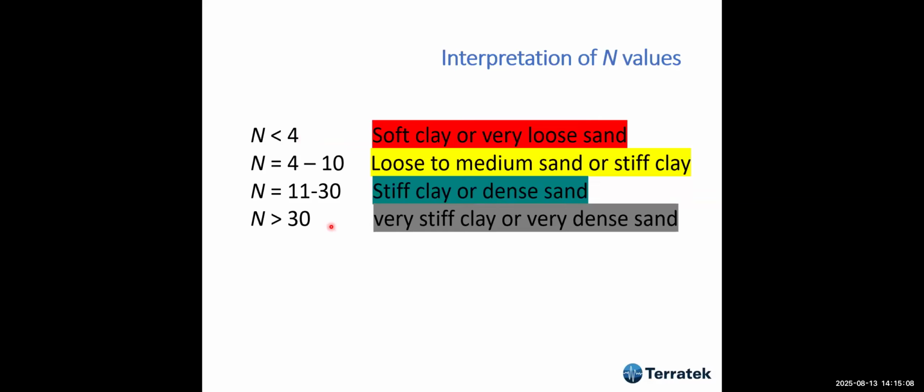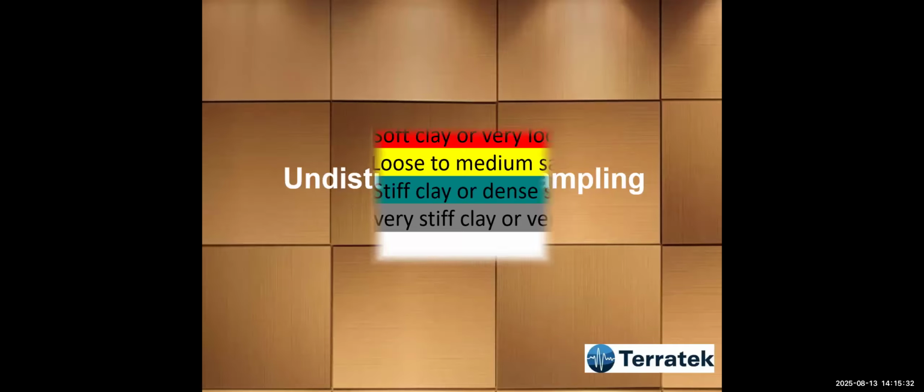So this is more or less when we have an SPT of 10, the soil is going to deform not very much, in most cases, not all. If you're looking at a bridge or something like that, in which we have very high loads on the piles, these piles should usually be bored into the rock bottom with a socket, okay?